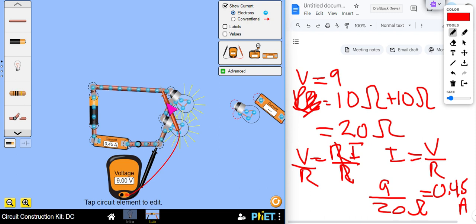Now notice what happens. So it says 9 volts. Notice what happens when I put this here. It says 4.5 volts. You won't have to do any calculations or understand necessarily why that happens, but the positioning matters so that we're trying to detect, again, the portion coming out of the power source and back to the power source. Positioning this here is not positioned on the way back to the power source. It's positioned in the way getting to the second light bulb. When we go here, we'll find the full potential difference of 9 volts.